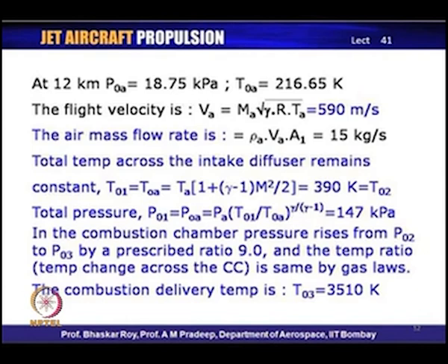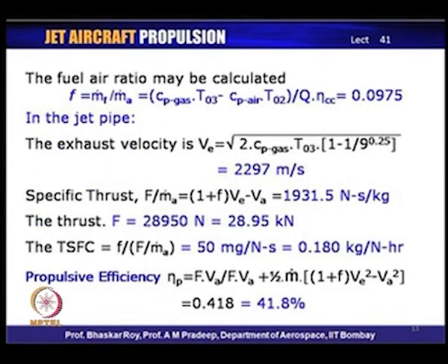So, if you do that, you can now calculate what the fuel air ratio would be from the prescribed temperature values. If you put in what we have done before, the fuel air ratio can be calculated from the heat that is generated by the fuel heating value that is prescribed, the combustion chamber efficiency that is prescribed, and this comes out to be